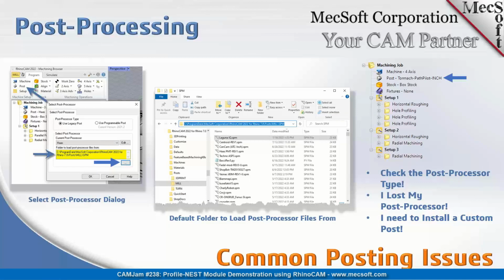Now, some common posting issues. I mentioned this dialog here on the left. If you go to the program tab in the CAM plugin and select post, you'll see the select post processor dialog. Again, I highlighted it in yellow. That's the default folder where your posts are when you load the product. So that's the location of the folder that you see in the middle dialog here. If you look at this string highlighted in blue, that's a folder path.